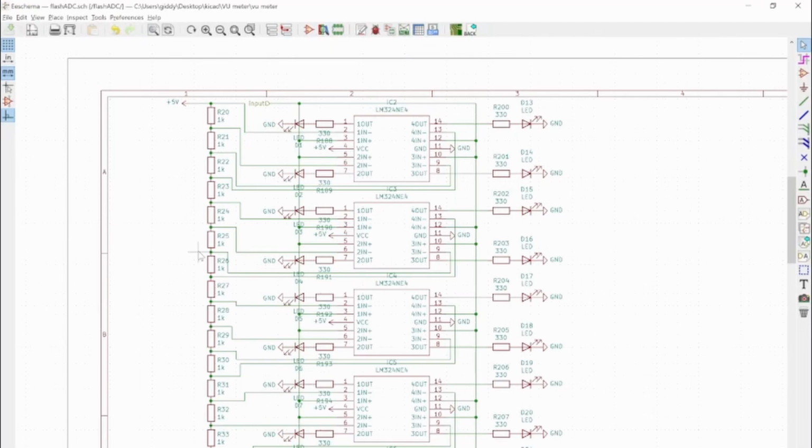So you may have also noticed that the top LED never turns on, because that one's still comparing the original signal with the 5 volts, and that never happens. So I guess the first improvement we could make here was to add the resistor to the top, before this first 1k, and that would mean that we'd have the full range.